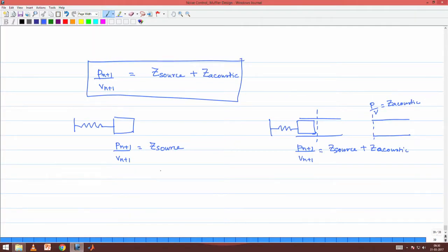So, the driving factor for the acoustic field is the vibration of this mass. The mass in turn vibrates because of the force. So, the fundamental excitation source for both the vibration as well as the subsequent acoustic is that force which in turn is related to the pressure Pn plus 1, right. So, the fundamental source in our case is going to be Pn plus 1, right.